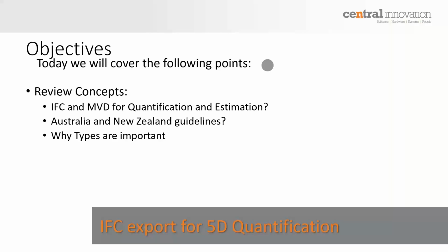Then we'll take a brief look at why types, and here we're referring to the IFC types, are important, and material definition, because obviously those two things will be essential for quantification. And even though those two things might not be explicitly defined or required in those guidelines and the IFC schemas, those will be important to facilitate the job down the road.